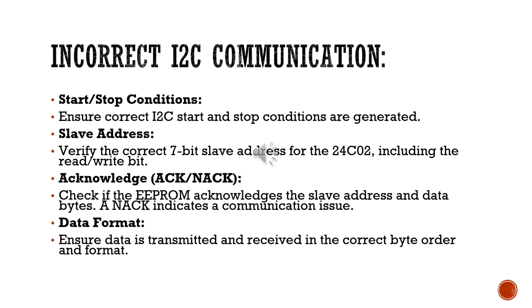Ensure correct I2C start and stop conditions are generated. 2. Slave address. Verify the correct 7-bit slave address for 24C02 EEPROM, including the read-write bit.